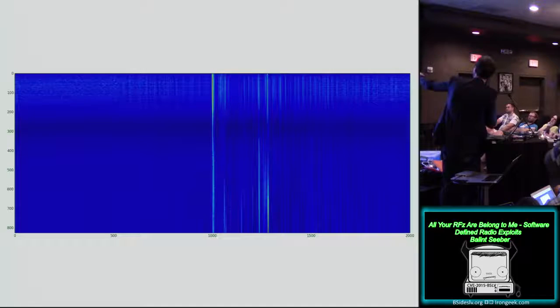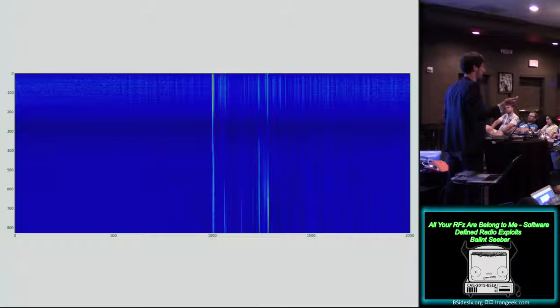And so this is offset by, whatever, 60 samples, which translates into maybe microseconds' worth. But this is actually showing you that you've got one strong signal coming in, and then maybe two other ones arriving, say, 5 and 7 microseconds later. So this is actually telling you how many reflections you've got coming in to the one point where you are.